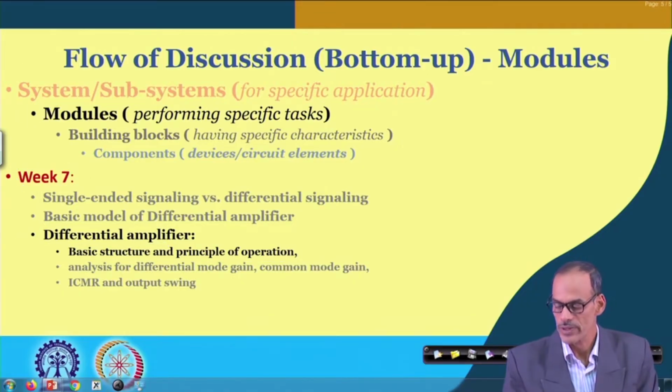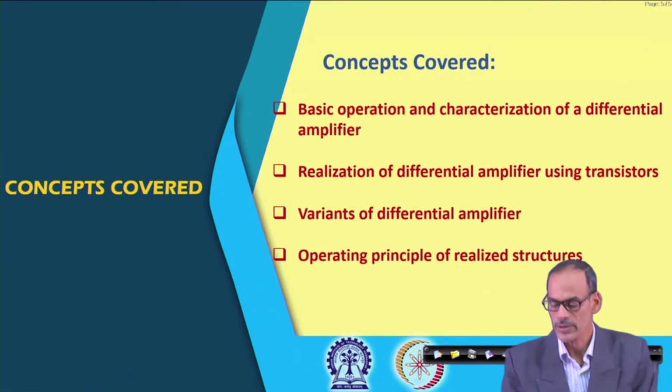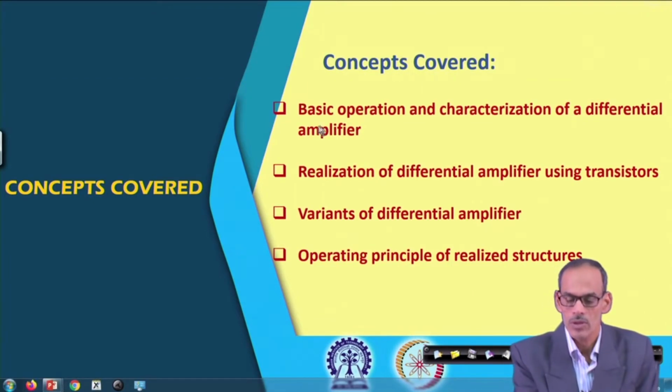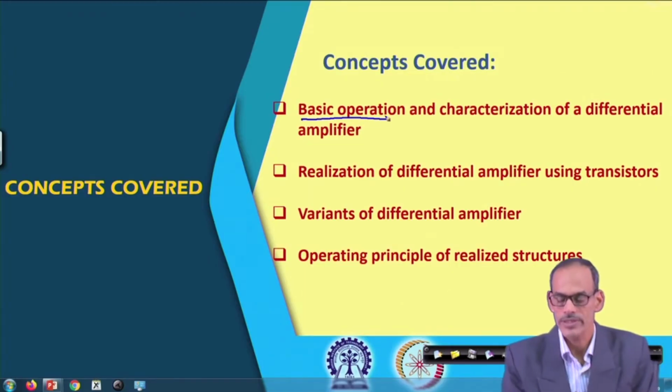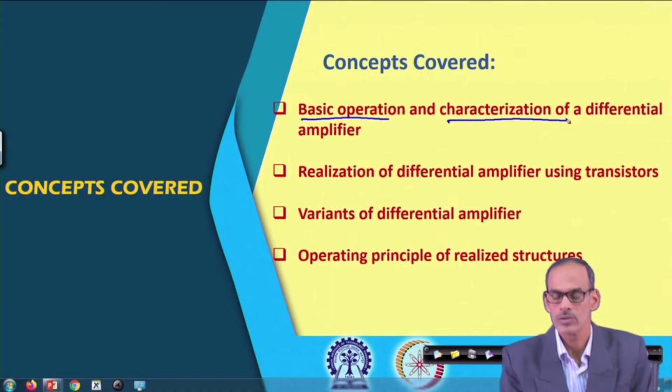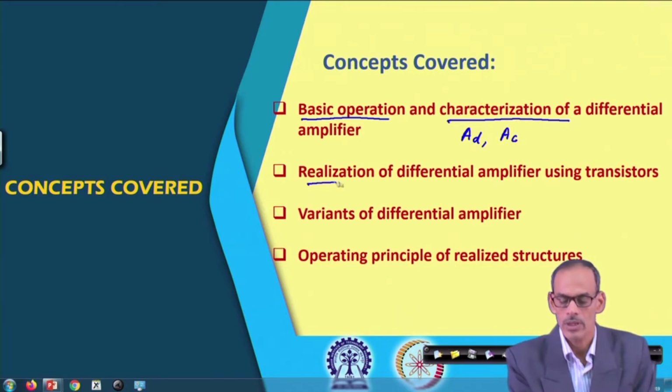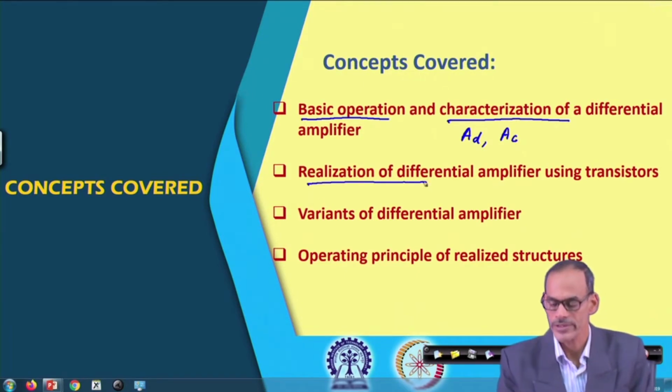The concepts covered in this lecture are the following. We are going to start with the basic operation, and then discuss the detail of characterization of the differential amplifier, namely how we find the basic parameter values, particularly differential mode gain and common mode gain, from a given circuit. Then we will talk about realization of the differential amplifier at transistor level.